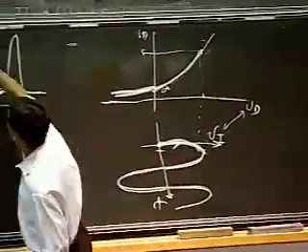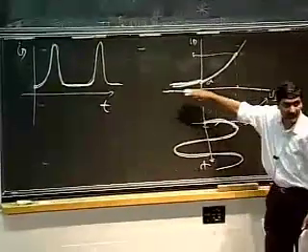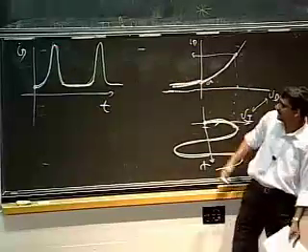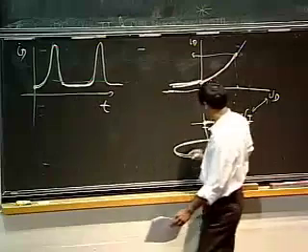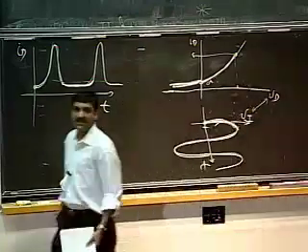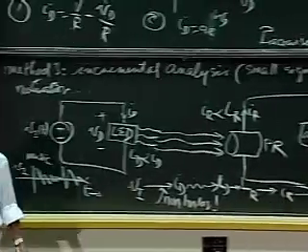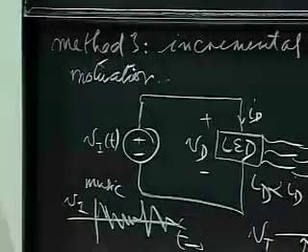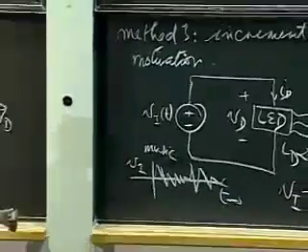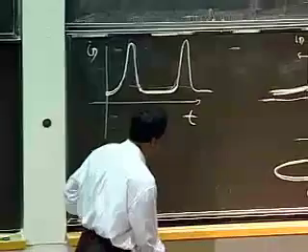So I get high rising peaks corresponding to these two. And for negative going currents, negative going voltages, it simply compresses them to a low positive value here. And that's what I see here corresponding to negative excursions. So if I input sound here, when the sound has negative going excursions, it will simply scrunch them, but will more or less let the positive things through, and that is going to give rise to a bunch of distortion in my signal.